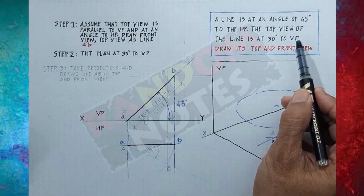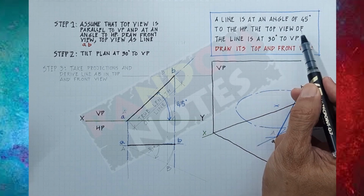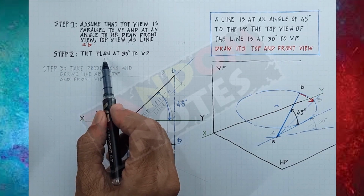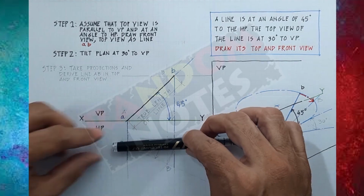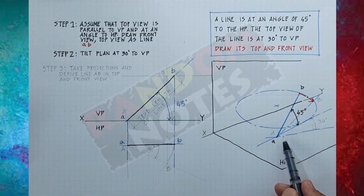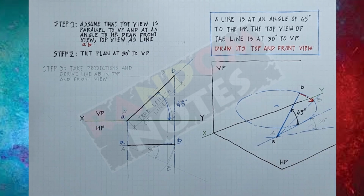Now taking the next condition which is given in the question, the top view of the line is at 30 degrees to the vertical plane. So we will tilt the plan of the top view at 30 degrees to the vertical plane. So this is here, and now this will get tilted at 30 degrees, which we have done in this also. We have tilted it by 30 degrees.